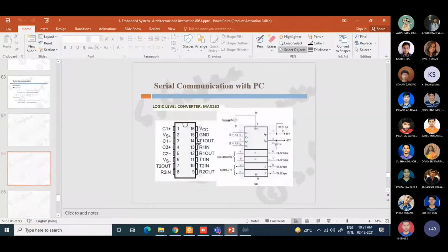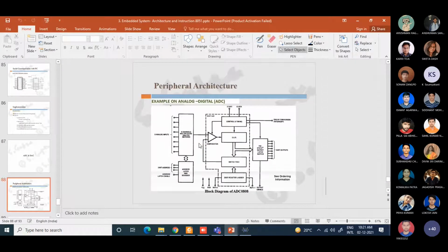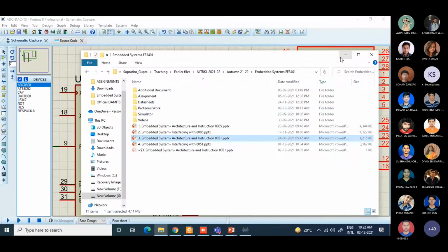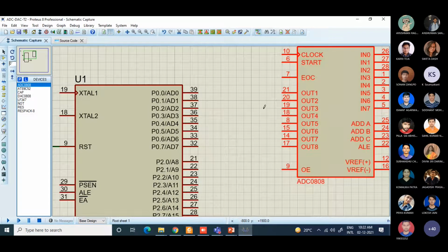You can see it from the data sheet, right? So you find 17 is the LSB and 21 is the MSB. Okay. So if I connect 21 into this, it will not work, right? So what is needed is that we need to connect these to MSB P7, and then there will be a crisscross.